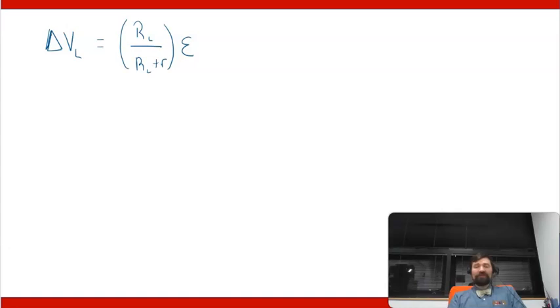So for small values of the load, as you increase the load resistance, the terminal voltage increases nearly, though not quite, linearly. If you make this sufficiently small compared to the internal resistance, then it will look pretty linear. Like if this is 1,000 and this is 1 or 2 or 3, it'll look pretty linear in that regime.